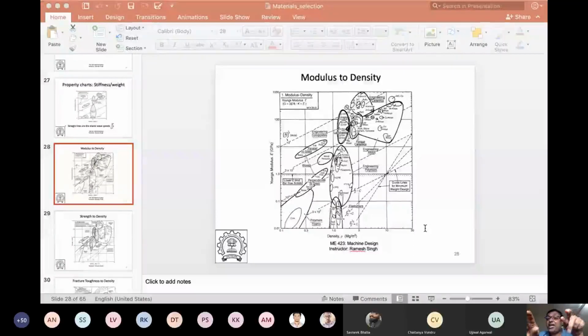But at the same time, a lot of these engine components, which people want to make, silicon carbide, so very high temperature engine components, people are moving to ceramics actually. So engine components, people are trying to make ceramic. A, it will be lighter. B, you can go to temperatures which are unimaginable with metals. So silicon carbide composites, if I can make it reliably, if I can make sure that it doesn't crack, right? If it has a reasonably good amount of fatigue life, I will actually make super high temperature engines. So people are trying to look at that. So that's what I'm trying to say, that if I can address some of the issues, I should be able to use it. Okay. So modulus density is one of the things.